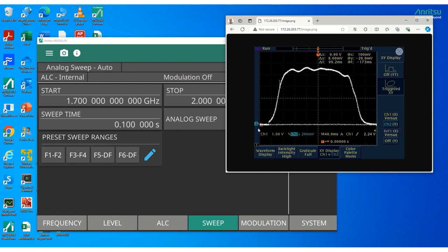As I was mentioning, the ramp signal, the horizontal output signal, is driving the x-axis in the XY mode, which is channel 1. It is set to 1 volt per division here, and as I had mentioned before, the horizontal output is plus 10 volts at the peak.